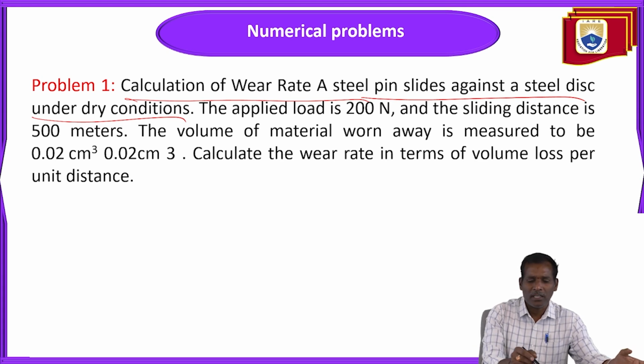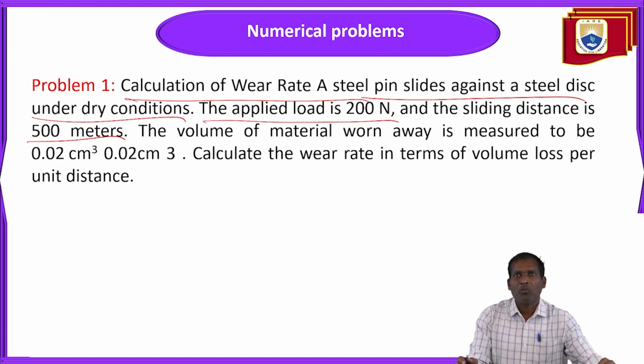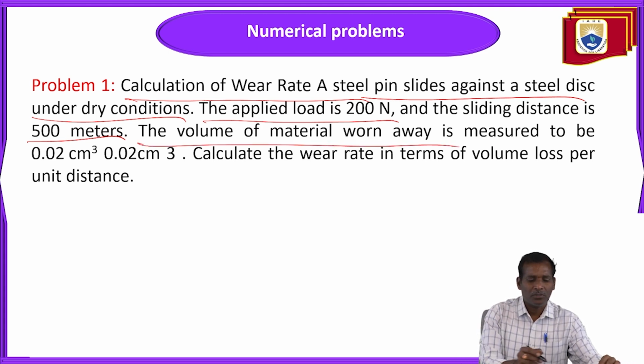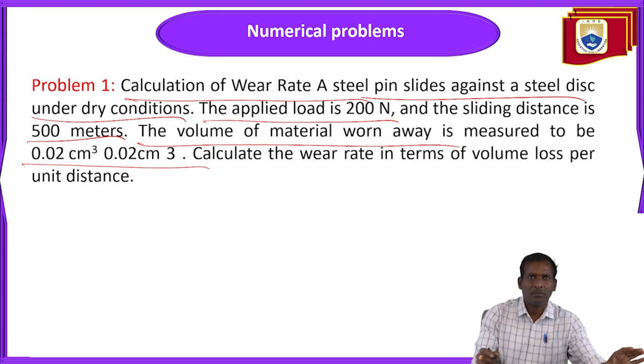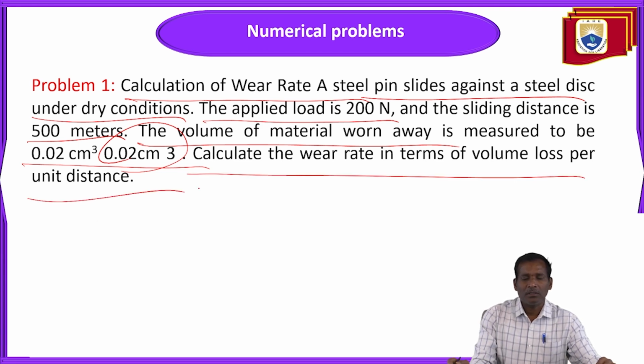The applied load here is 200 newtons and the sliding distance is 500 meters. You can adjust the distance also, as you can see in the pin on disc experiment. The volume of material worn away is measured to be 0.02 cm cube. Calculate the wear rate in terms of volume loss per unit distance. So what he has asked is to calculate the wear rate in terms of volume loss.